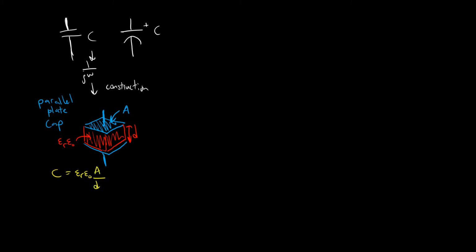And even though this is like the most simple capacitor, it really contains the insight you need to understand how capacitors operate, right? There's two plates, some distance between them, and there's some area with some dielectric. And none of these materials in practice are ideal, right? So the metals are going to have finite conductivity. The dielectrics won't be perfect insulators, right? And maybe their properties vary depending on the voltage applied to them, right? So it doesn't always end up being perfect. And as a result, we end up with non-idealities.